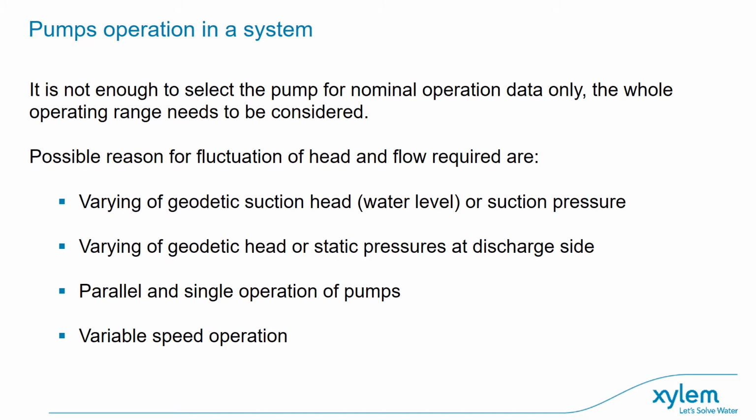And also, how many pumps are in the system? Have we got pumps operating in parallel? Have we got duty standby, duty assist standby? What's the criteria? Have pumps been sized for 50% of the duty or 40% or 100% of the duty? So all these things need to be taken into consideration.